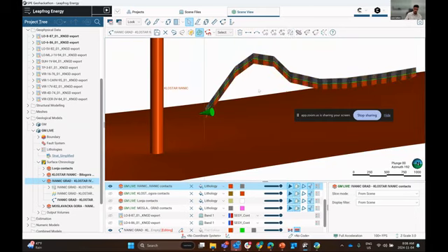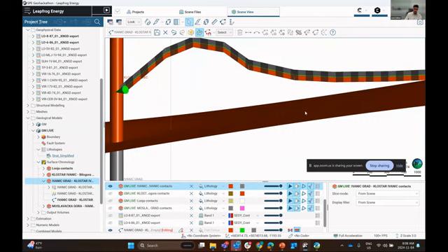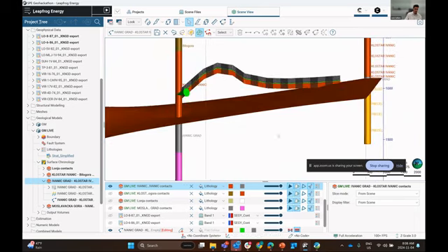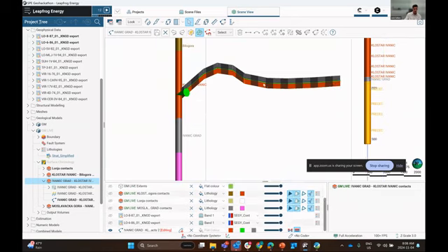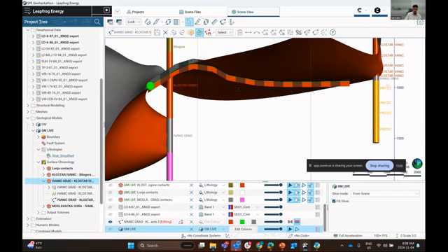So if you switch the polarity, this shows red on bottom, gray on top, where if you're creating a stratigraphic sequence where red is actually in the real world on top and gray is on bottom, if you inform the structure of this surface with a polyline with the reversed polarity, you can get quite interesting results. So if we were to save this and register that into our polyline building tool, you can see that this has been totally flipped on its head.